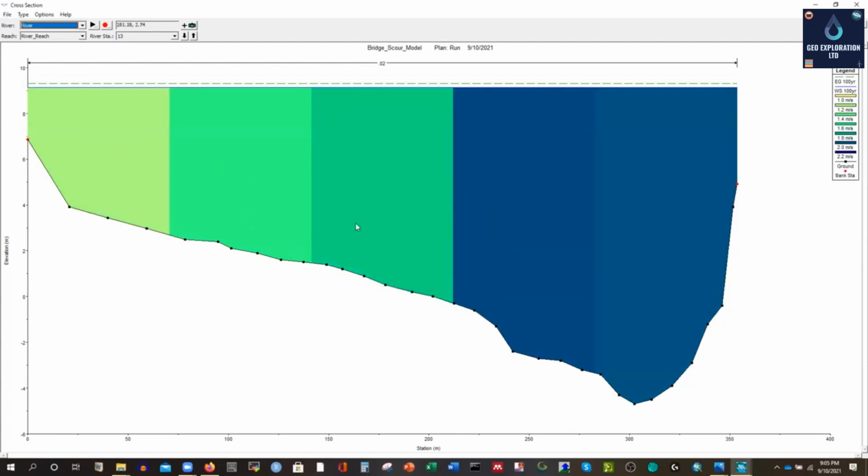We have the higher velocity because it is a kind of bend. That's why you can see this is the inner bend, that is the outer bend, and we have the deep portion there, right? So we know that for a meandering river, the deeper channel or the thalweg, the deepest point, is located at the outer bend. So here it is, and you can see the velocity is 2.2 meters per second, and this is how we can calculate the velocity.